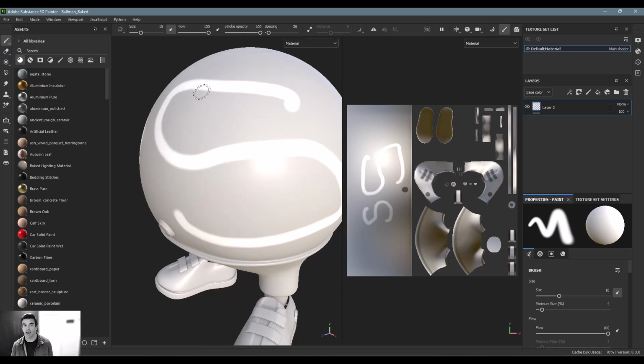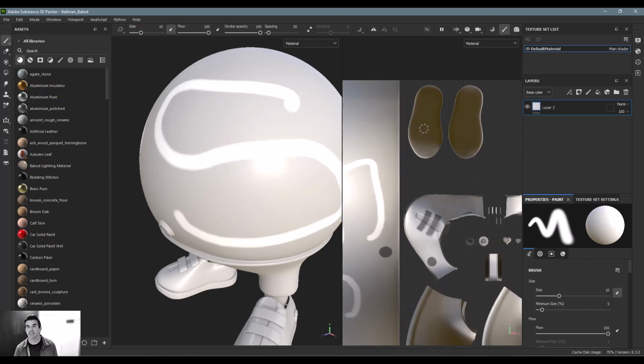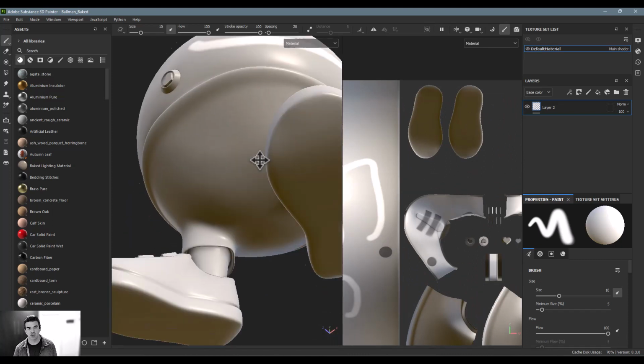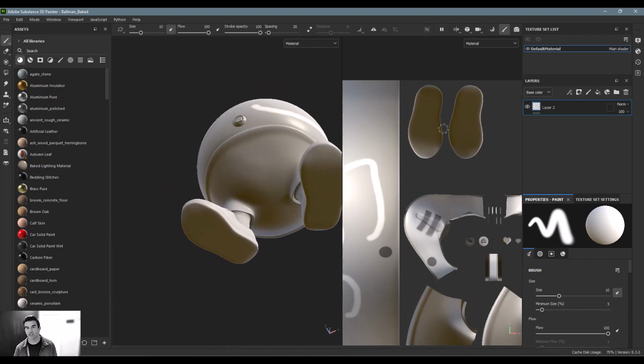Now, I mentioned on the import, if you haven't created these when you're 3D modeling, if maybe it's a CAD model that doesn't have UVs and you export it as an OBJ and you're ready to import it here, you can automatically generate these. Because what you're looking for here is, again, every individual component laid out flat with space between them. Because if, let's say, the bottom of these two shoes were over top of each other, if I painted here, it would go on both of them. But since they're separate, I can do them individually.